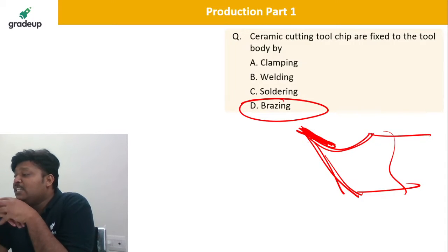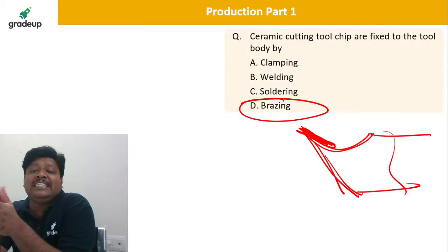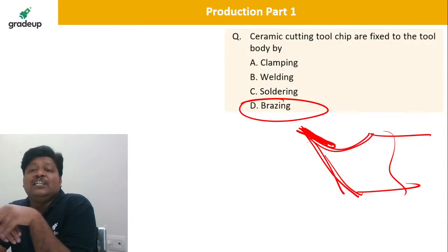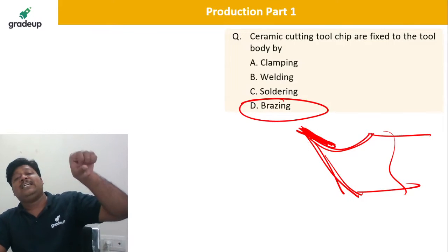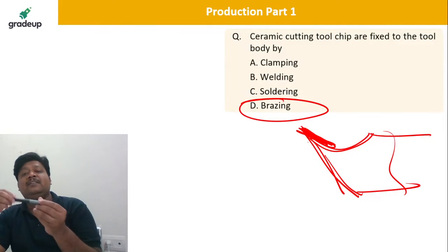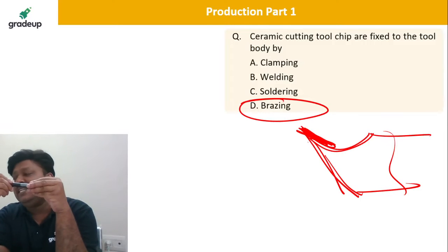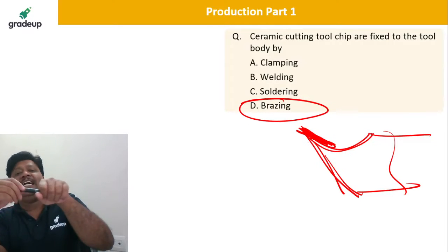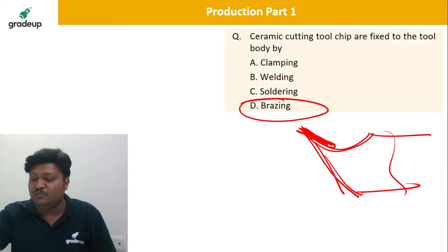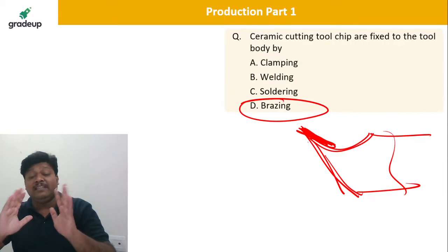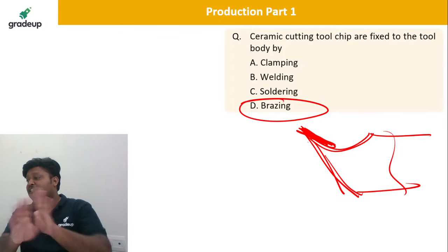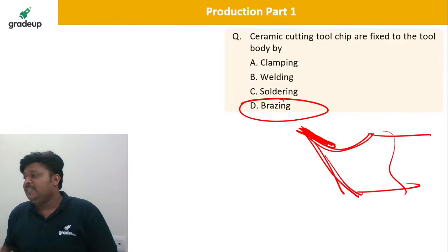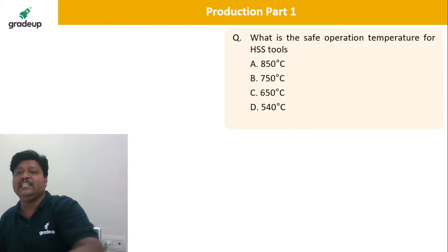Here, Ajju, what you are saying is, see, friction welding is used when there are circular bodies. For example, if I want to attach the drill to the shank, in that case you can use friction welding. Circular symmetry, that is very important. Circular symmetry should be there, then friction welding is okay, otherwise not okay. Thank you, Savan. Take the next question.